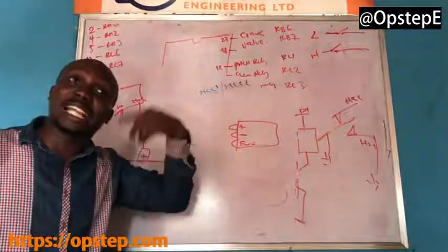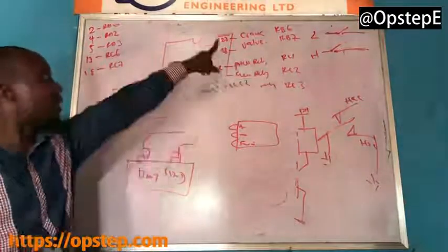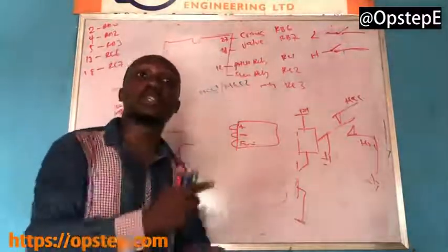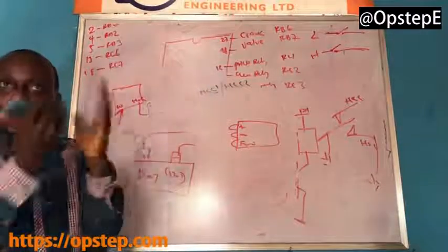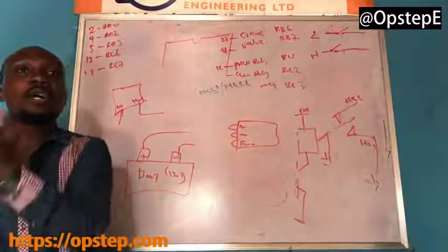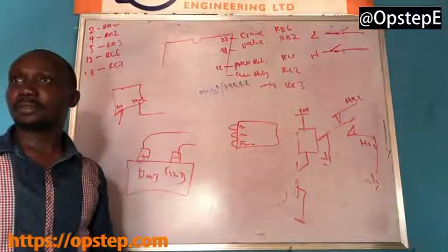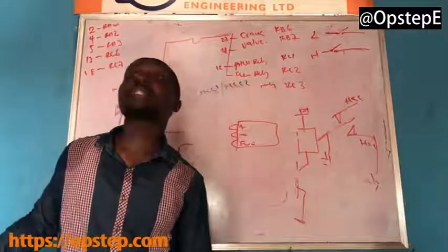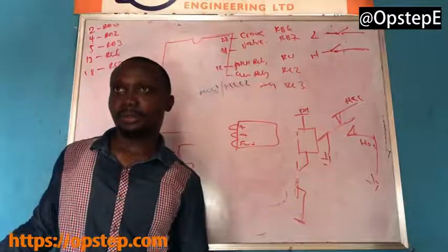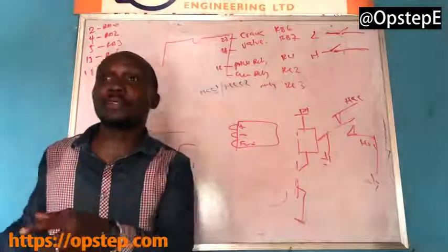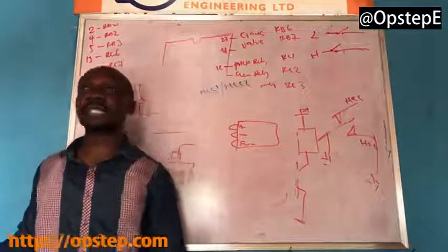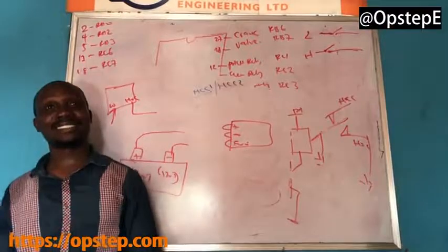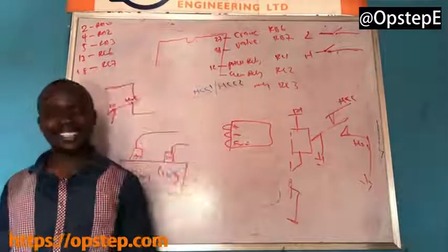Now, the moment the generator starts and the crank stops, that valve must remain on. If you now want to turn off the generator, all you need to do is turn off the valve. It closes, the generator requests for fuel, there's no fuel, and it goes off. Did the gen go off instantly like that? Instantly, like a petrol gen. Diesel will go off almost immediately. And let's be frank, how much is immediate? It can be up to 60 seconds.